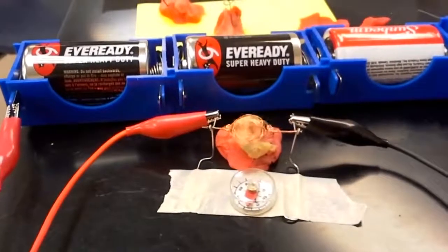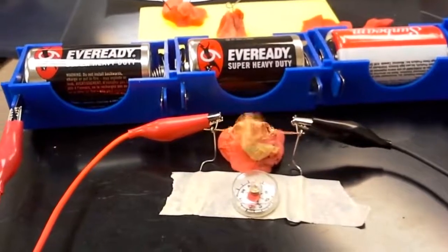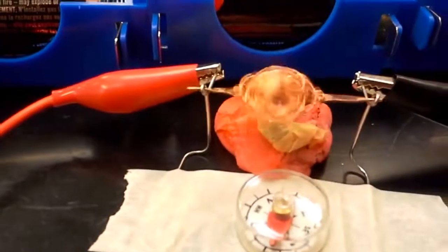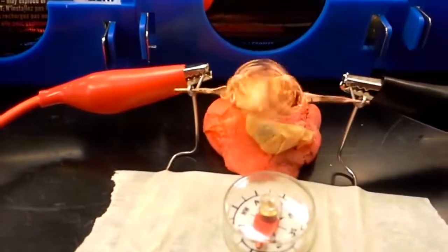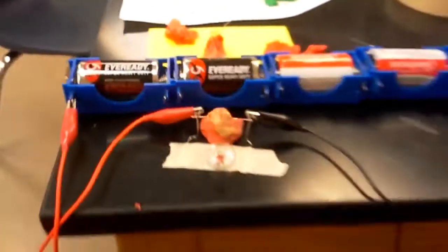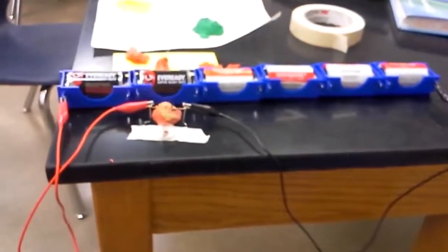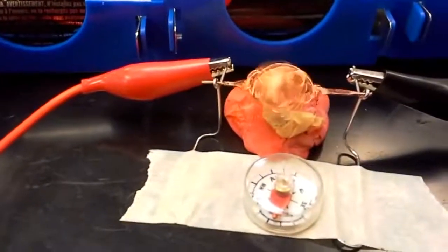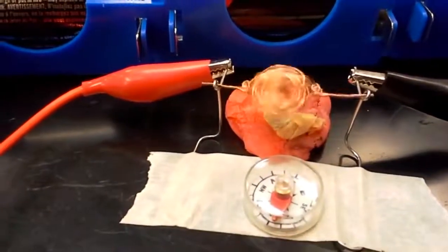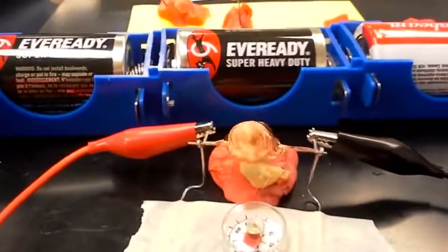So what's happening here? I have a small electric motor of the type on scitoys.com. It consists of a coil of wire with some special insulation, which we'll talk about in a little while, a magnet, it's in that bundle of masking tape, and a DC current caused by a 9-volt battery, which is here, 6 D cells. And as you can see, all of that alone is enough to keep the coil of wire spinning. So I'm going to stop it, and we'll discuss what's going on here.